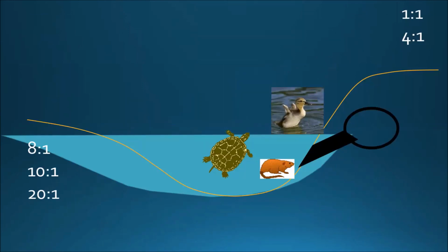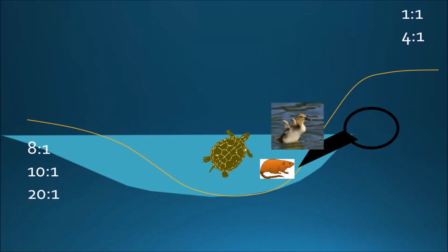So in designing the wetland, these types of details and impacts should be considered. And it is also important to consider not only how deep the water is, but how steep the slope is to get to that deep or shallow water. In the early days of wetland work, it was not uncommon for embankments or potholes to be constructed with steep slopes. These were typical of other structures we did, but they do carry some hazards. In addition to erosion concerns, it can be difficult for wildlife, particularly small wildlife, to get out when all of the slopes are too steep.